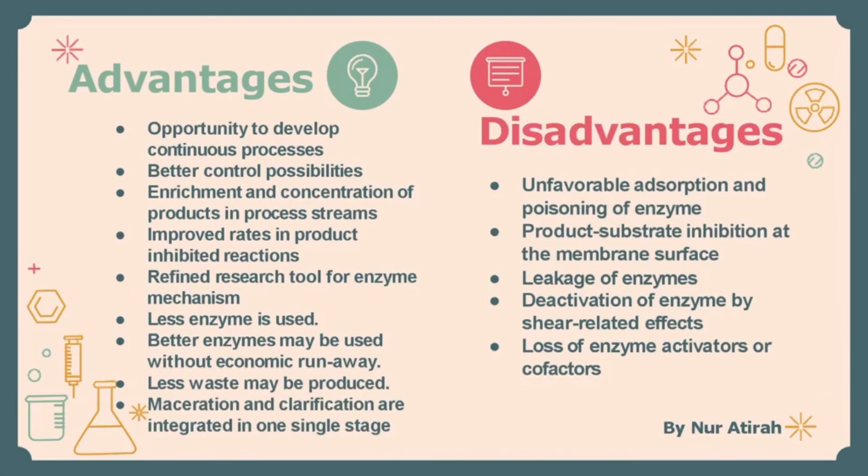Among the advantages of using an enzyme membrane reactor is the opportunity to develop a continuous process. Next, the possibility of better control. In addition, the arrangement and concentration of the product in the process flows. Thereafter, an increase in the rate of the reaction as product inhibition is reduced. Further, less enzyme is used, which is also one of the advantages.